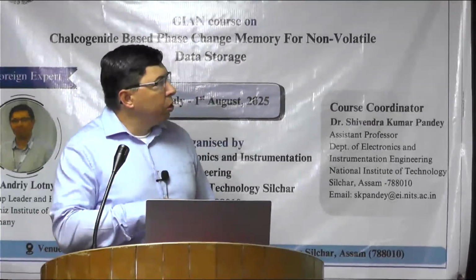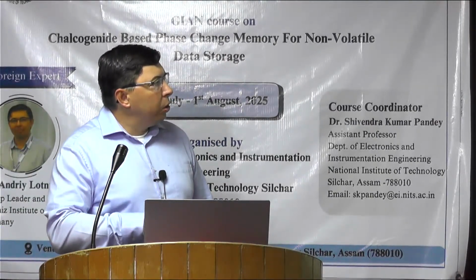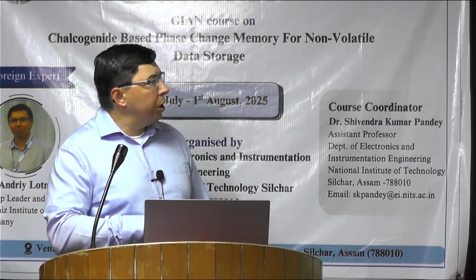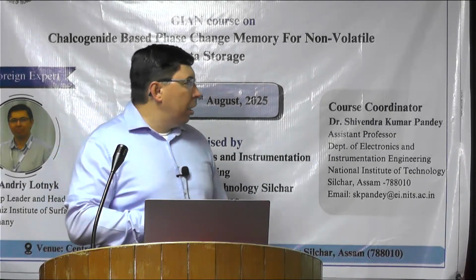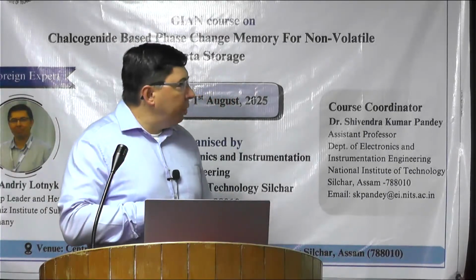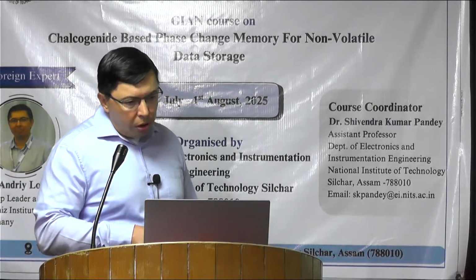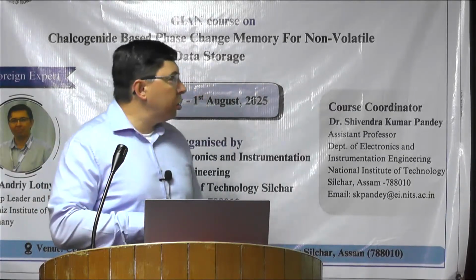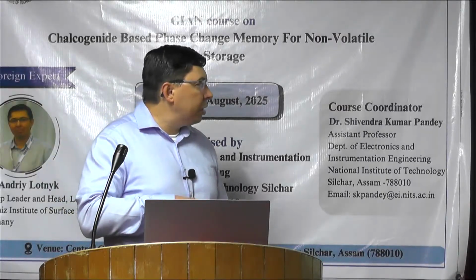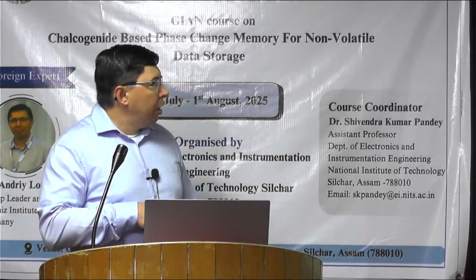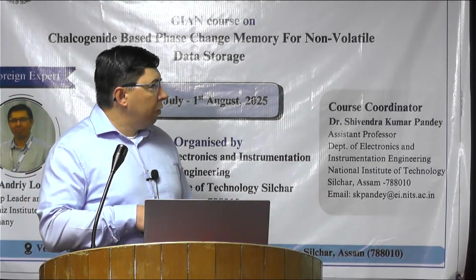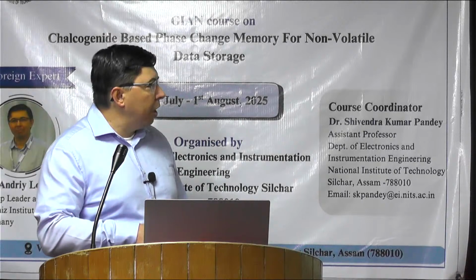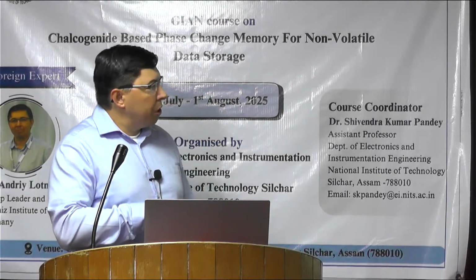As I said, it was compositional dependent. You can see here the value reduces from 0.1 to 0.6. Then the B, this is the Tauc parameter, which represents also disorder in the system. It's also temperature dependent for GST 2 to 5. For example, it's reducing from low temperatures to the higher temperature, and the band gap is also temperature dependent.